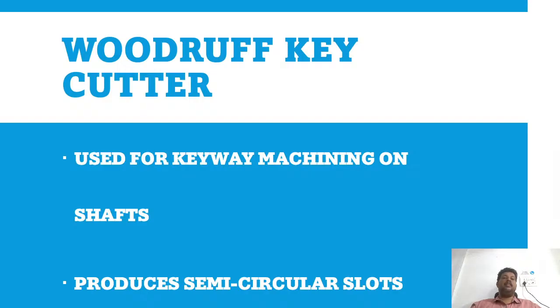Now, the Woodruff cutter is specially designed to create a semicircular keyway, unlike a normal slot. This is not straight at the bottom, it has a curved profile. Because of this shape, the key gets better seating and alignment. So, whenever you're working with shafts, gears, pulleys, and you need a proper locking arrangement, this tool is used.